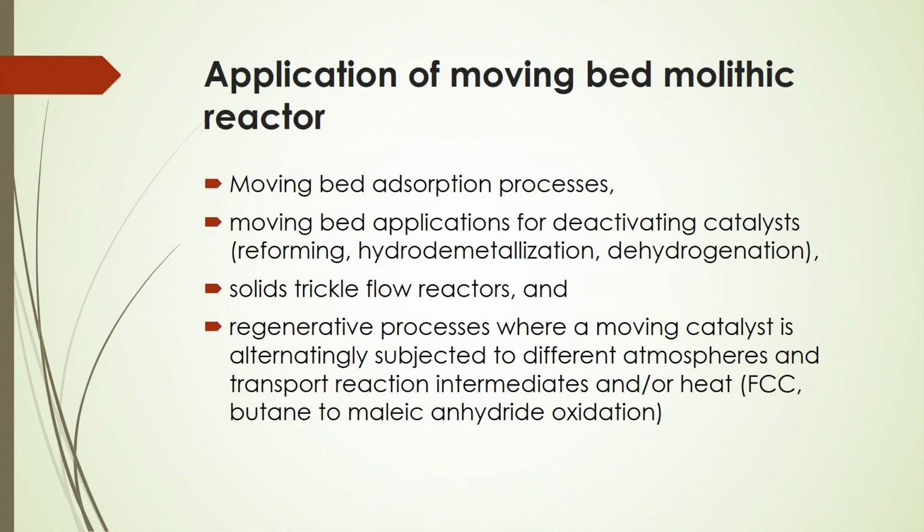In that case, you can use movable reactors instead of these monolithic reactors, but sometimes the hydrodynamic aspects may give a disadvantage to the trickle bed reactor in this movable condition compared to the monolithic structure, because the transfer of gaseous components to the solid components depends on energy transport there.